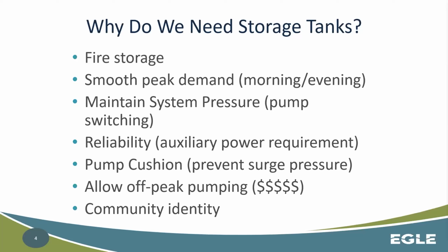In that same idea of smoothing out those peak demands, you're also allowing off-peak pumping. Especially if you're purchasing from somebody, there are high times when pumping or getting water delivered to you is going to be more expensive. So if you can do that during off times, that's going to be more cost beneficial to you. You can do that at night, fill the tower overnight, and then continue on from there.